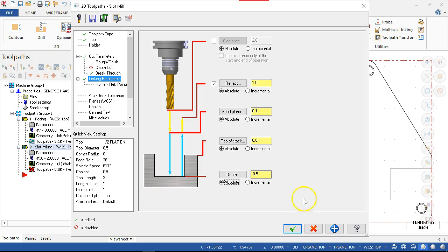All right, when we have a need to get to that next level a little bit faster as opposed to feeding, then we'll use the incrementals. I'm sorry, if you've got, in this case, a pocket, and you're going to do it in one step? Half inch with a half inch tool. It's going to be a little aggressive, but yeah.